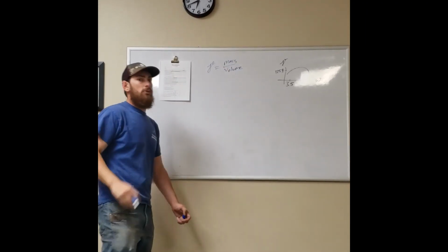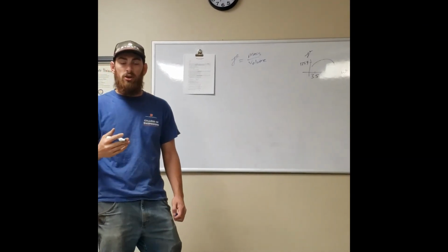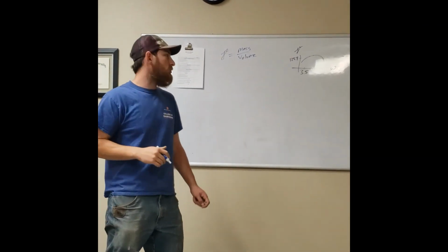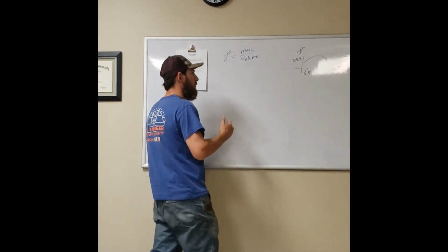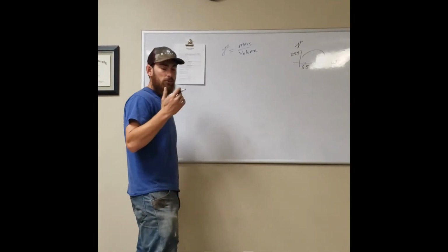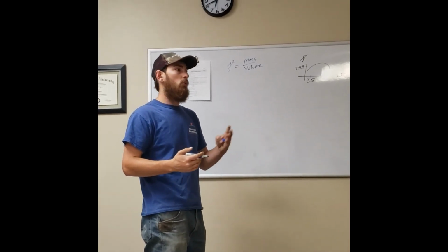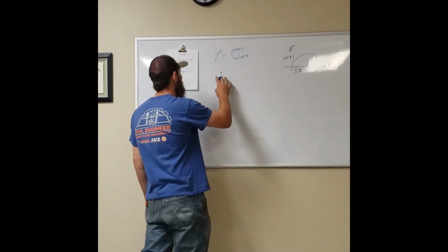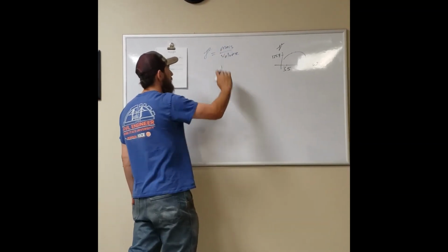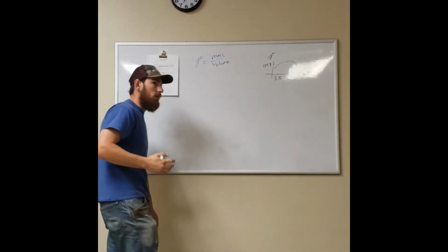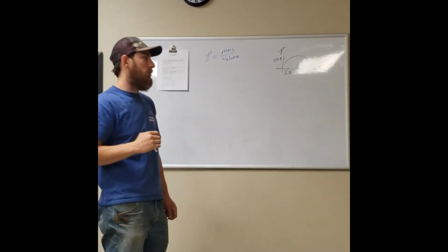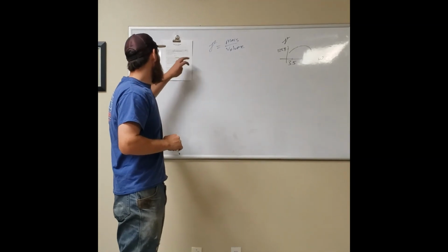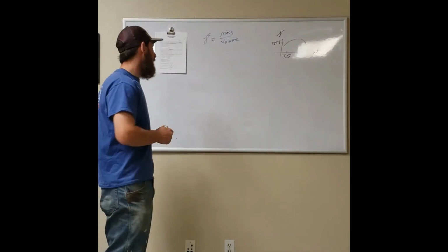So what I'm going to do is put the sand in the sand cone and let it run out into a Proctor mold. I will get the weight of the Proctor mold beforehand, and the weight of the Proctor mold with this sand in it. If you subtract the two of them, that'll give you your mass divided by the volume, which for the Proctor mold, again on the 4 inch, is 0.0333. And that'll give you the dry unit weight of the sand, because the sand is already dry.